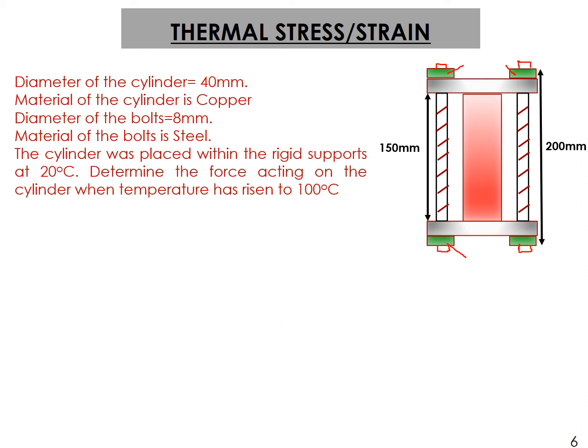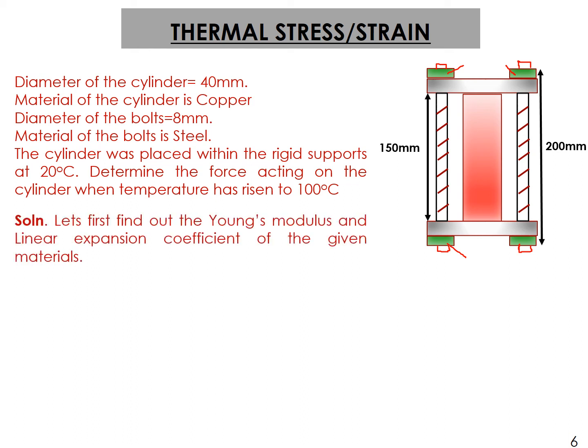Now, can you guess what force will be induced? Yes, because if the cylinder is free of supports, it will expand. That expansion is being restricted, so we will get a compressive force on the cylinder. Okay, let's move further. Let's find out the values of the materials, meaning the expansion coefficient and the Young's modulus, which is very much required here.